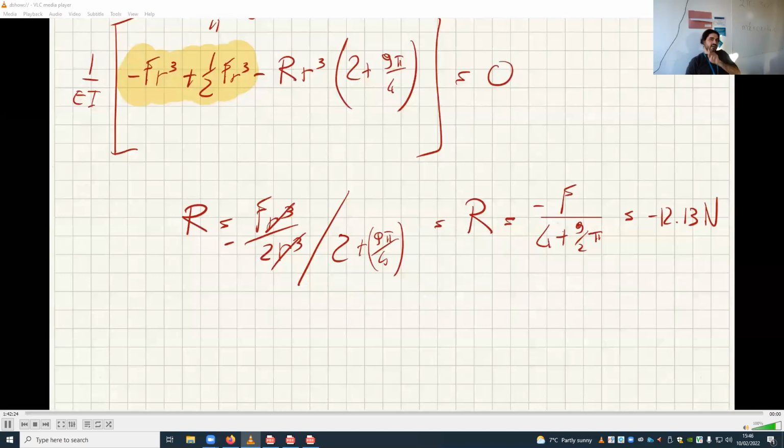If you integrate over the entire 360 degrees of the crank, you'll see what's happening to the piston during one entire cycle, and you'll find the entire velocity profile of the piston. From the acceleration profile, you find the velocity profile, and you find the displacement profile of the piston.